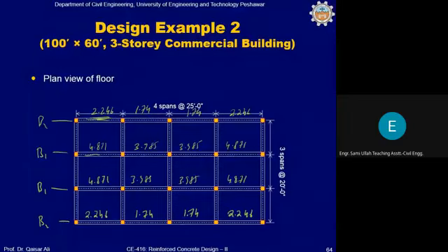Is that so? Can you hear me? Yes sir, yes sir. Okay, now with this you also add the self weight of the web. What is the cross sectional area of the web? The beam cross section was equal to 14 by 20 inch if you remember, and slab thickness was equal to 7 inch. So what will be the depth of the web?